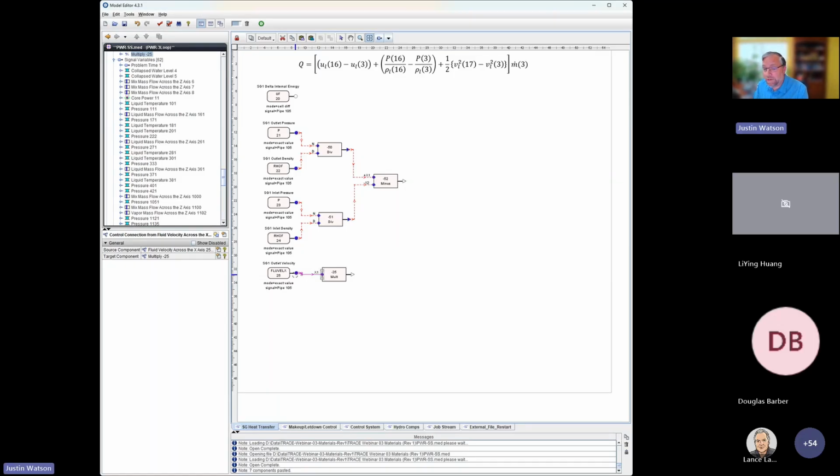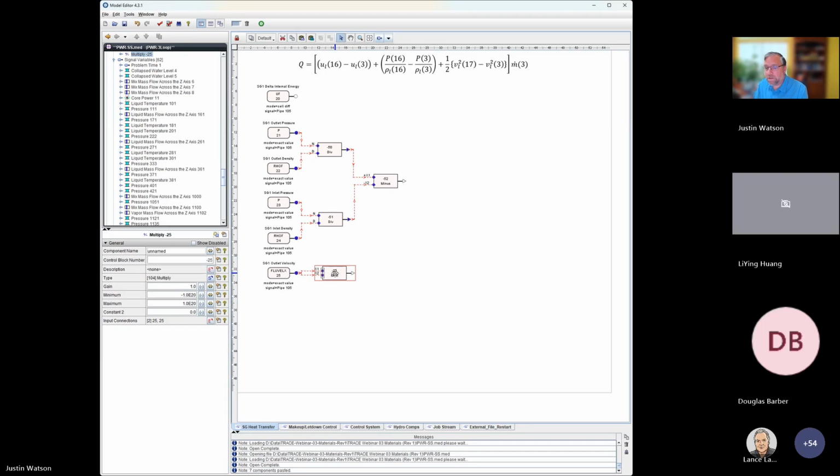If we want to do that again, we can click on the circle handle and go over to our multiplication again and click on the area indicated by this X when we see the blue dot. Now you'll notice that we have two inputs to this from the same signal variable, x1 and x2. So it'll multiply them together, effectively squaring this value. If we wanted to cube the value, we could make yet another connection. But for now, we just want to square it.